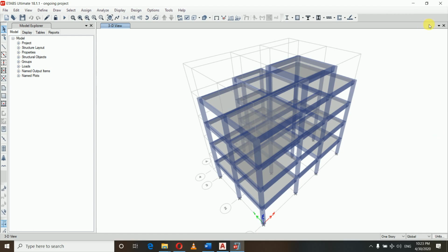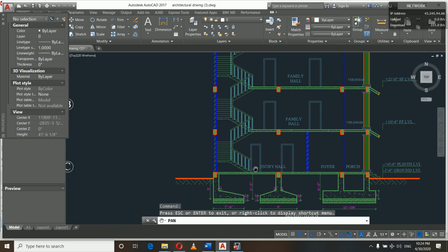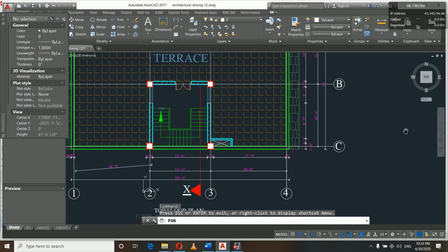For designing a staircase, you can see in the elevation portion, here this is the ground floor and this is first landing, here is the elevation of second landing. So this level and this level, we have 2 intermediate levels in between 2 floors. These 2 levels are known as intermediate planes, that are reference planes. So we will first be defining these reference planes, and then we will have to define the reference points. What are the reference points? The reference points for these slabs, and from where our staircase is going to start and end.